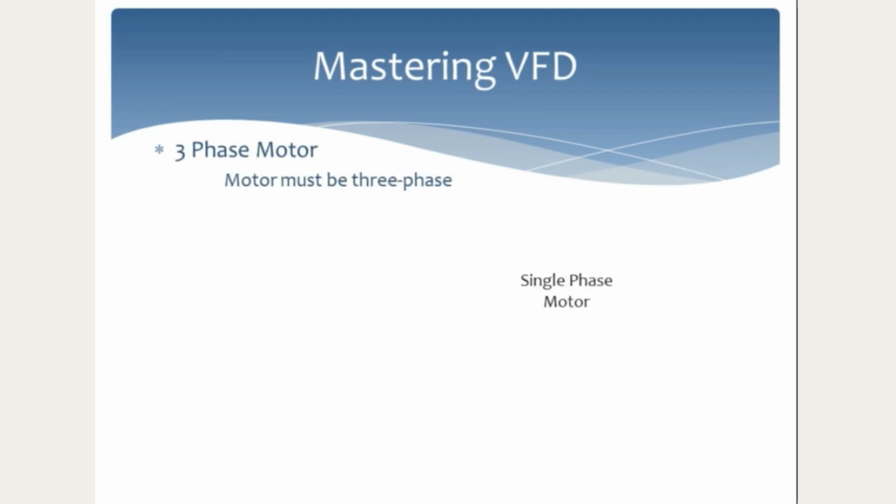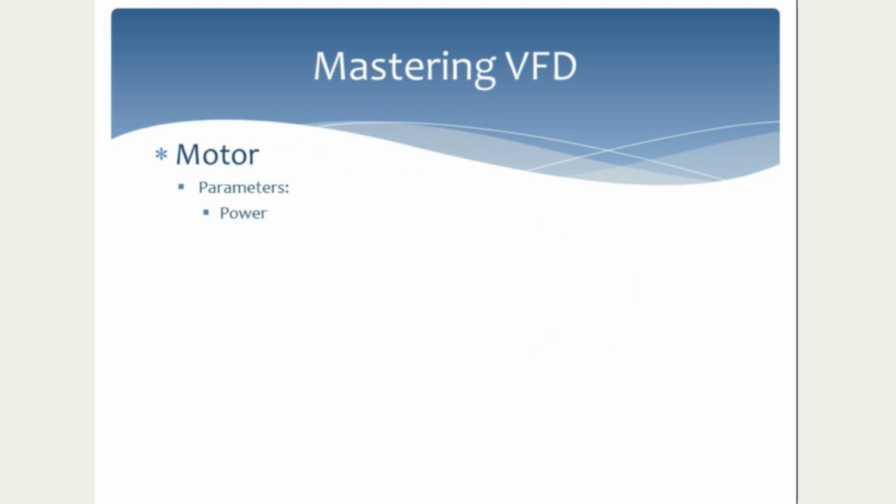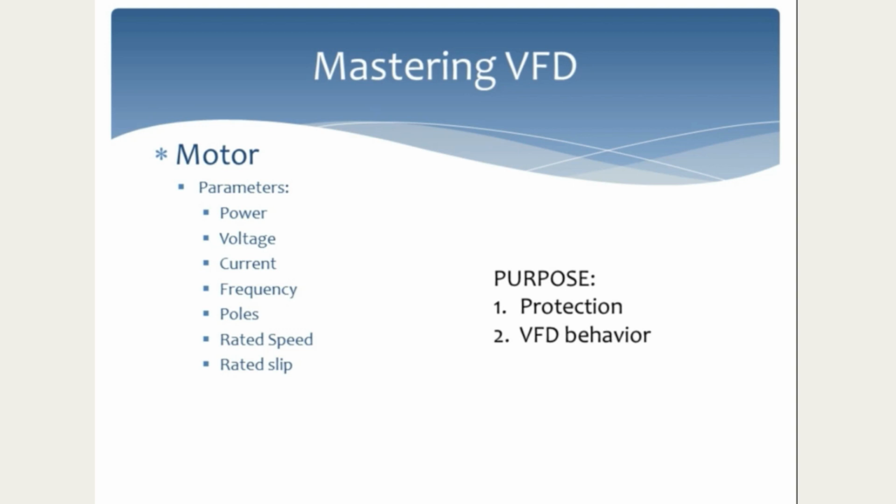VFDs are designed for three-phase motors, so a single-phase motor cannot be driven with a VFD. We need to know the parameters of the motor. It is very important. Parameters like power, voltage, current, frequency, motor poles, rated speed, motor slip. We need to enter motor parameters in the VFD, which will help the VFD to protect the motor and change the characteristic of the VFD as required for the motor.